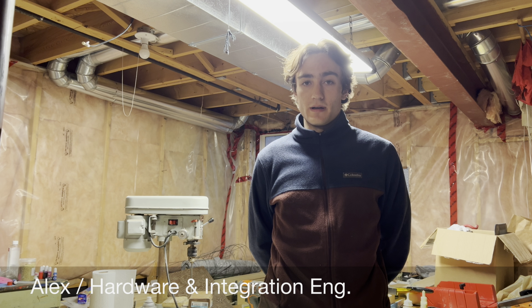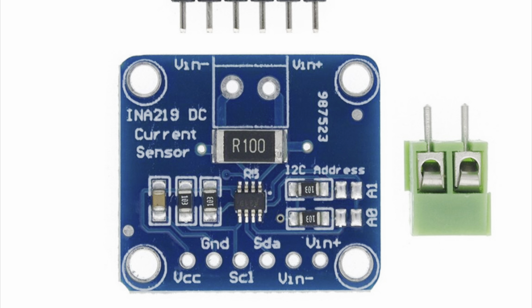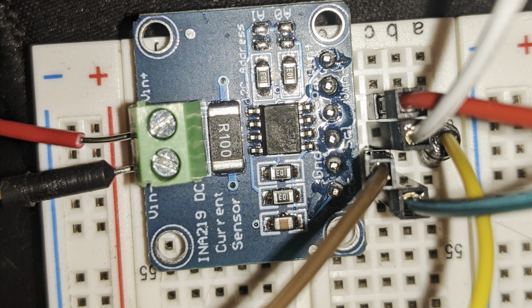In order to measure voltage, current, and power from the solar panel, an external device was needed as the Raspberry Pi does not have a built-in ADC. The INA219 was chosen as it can make all 3 measurements and serially sends the data back to the Pi via the I2C bus. The INA219 uses a 0.1 ohm shunt resistor between the VIN+ and VIN- terminals to measure voltage and current.